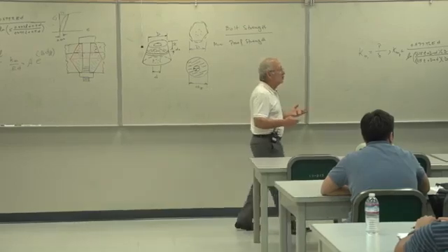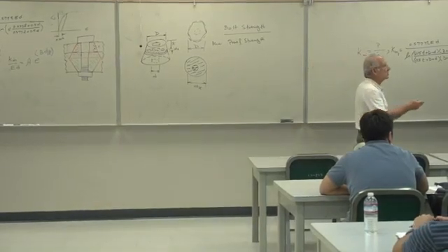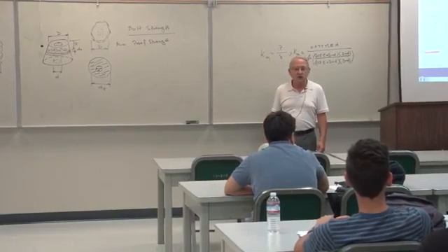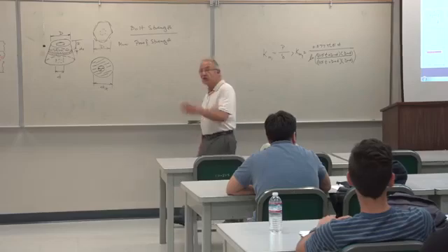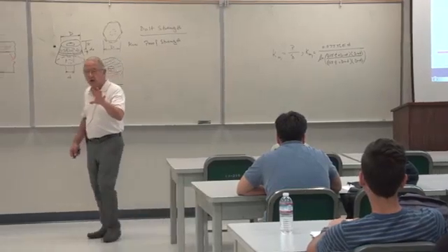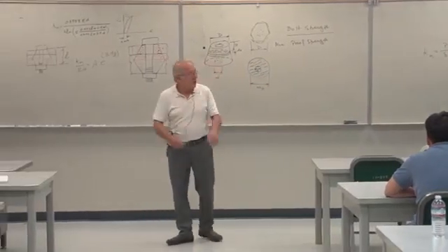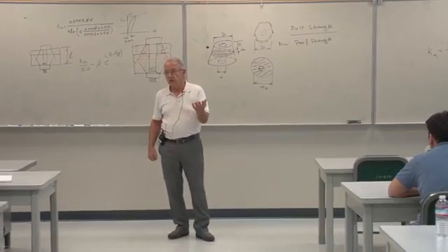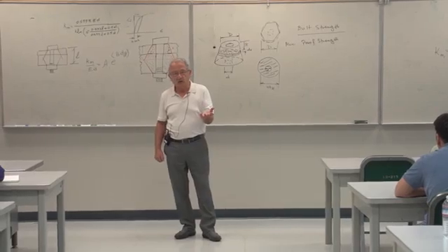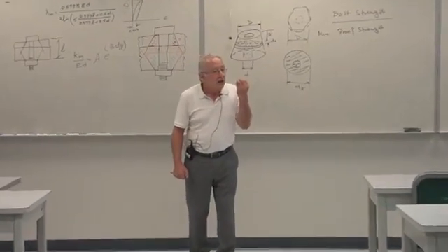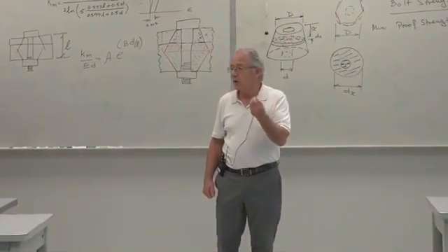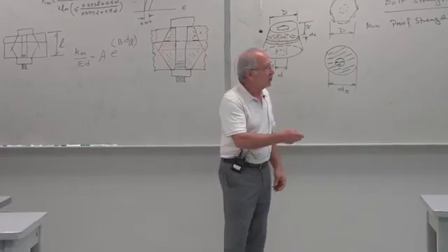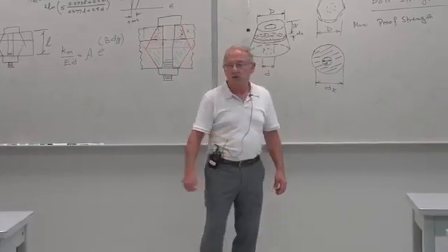Of course, in doing this analogy, we're assuming that this stop here is rigid. Doesn't deform at all. Well, that's not quite true for members. They do deform. So this is not to say that none of the externally applied load goes into the bolt if you have a preload, and this is our preload right here. Only a small amount of it goes into the bolt, depending on the relative stiffness of the member and the bolt.